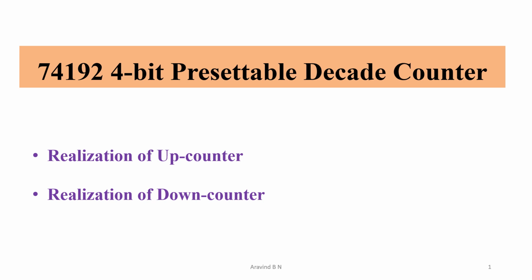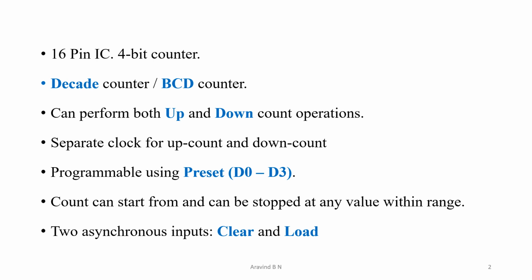In this lecture, we are going to discuss the details of the 74192 4-bit presettable decade counter. Also, we are going to continue with the realization of the up counter as well as the down counter using 74192. Let us first go through some of the details of 74192.